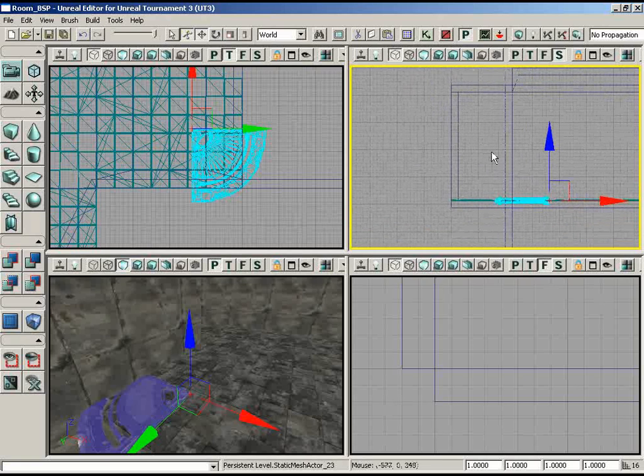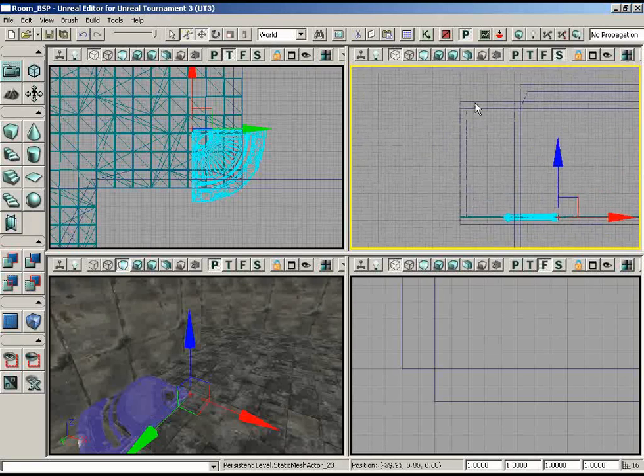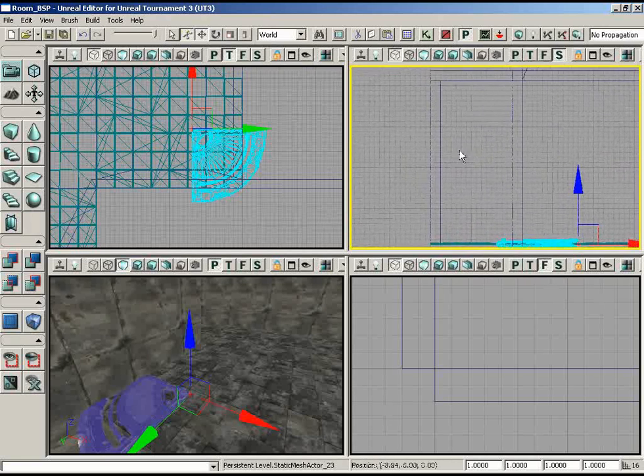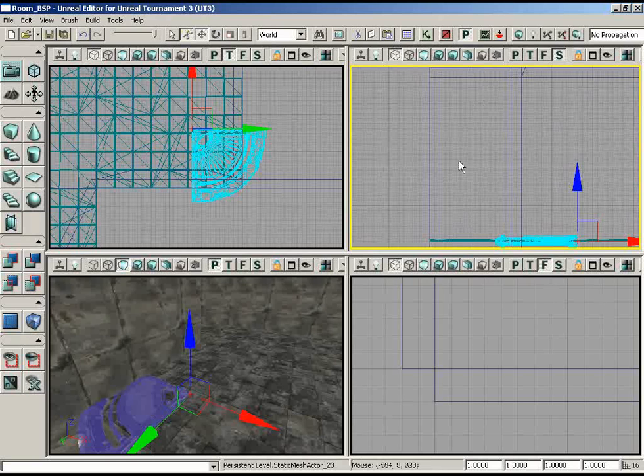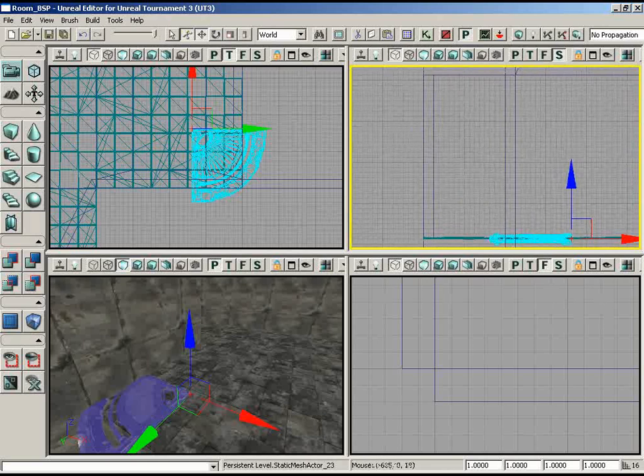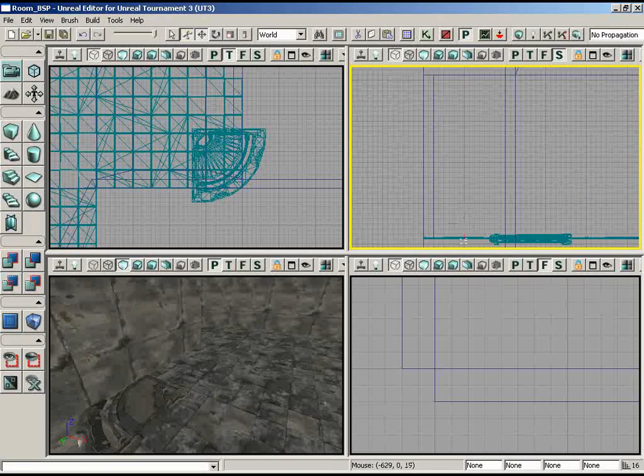Now, it's tempting to think that this major grid line is the exact center, but if we look at the ceiling really close, we can see that the ceiling doesn't lie on a grid line. So we're actually going to need to do some measuring to make sure we get this lined up right. At least not on a major grid line. Exactly. So what I want to do is go from the floor up to the ceiling, and let me move the view a bit so I've got everything in view. And measuring this, we do in fact have 512 units, which is what we intended by making the walls that tall. But we want to find the midline, and half of 512 then is going to be 256 for a midline, and that major grid line is at 240. We actually need to go up another 16 to make 256. So really, when we go to align everything up, we need to make sure that we hit 16 units above this darker grid line. Okay.